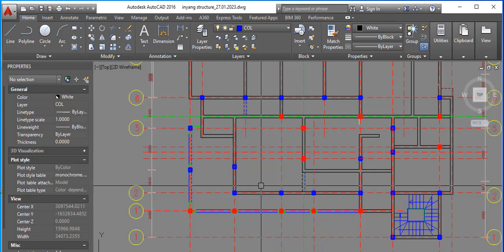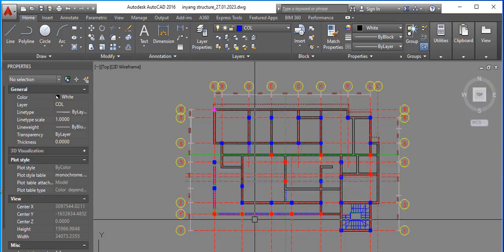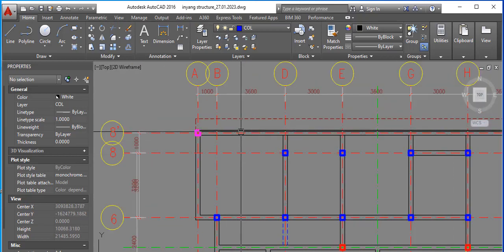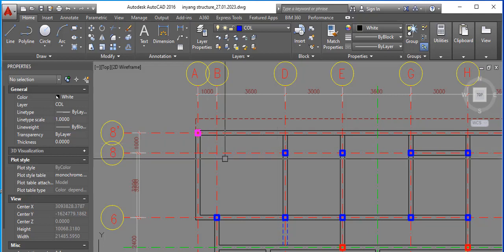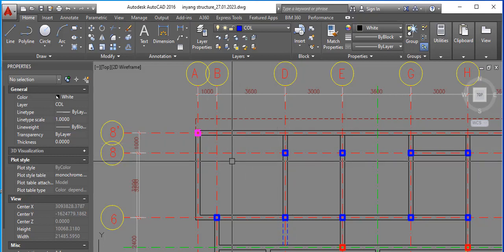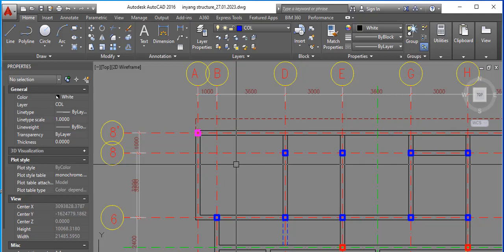On your roof floor, it's advisable, because the wood you'll be using for your trusses, they are maximum 4 meter long. So your spacing between your roof beam, it's an advice. It's not that it's a law. I advise that the spacing is maximum 4 meter or less than 4 meters.